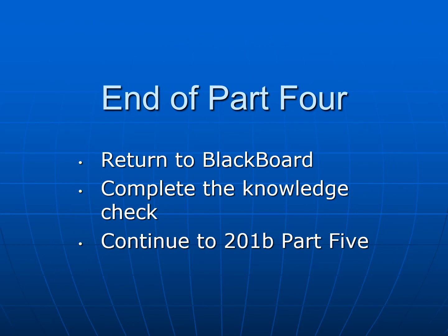You've now reached the end of part 4. What I want to make sure that you understand is how to represent your phasors on your diagram, whether it's an open arrowhead for voltage or a closed arrowhead for current. And I want you to understand the idea of in phase, being everything's at the same phase angle, or out of phase, and whether that out of phase component is either leading, it's ahead, or lagging, it's behind, whatever is on the reference line.